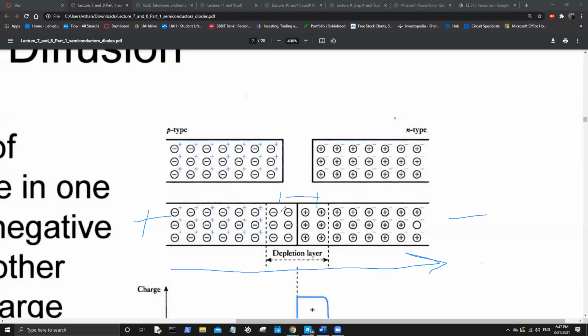But that's caused by an electrostatic effect. Now, I don't know if it's just electrons that do that. You could have an increase of electrons or an increase of positive charges, holes, but essentially it would be the same thing. What happens is your depletion layer decreases. So this equilibrium that used to be equal, you're breaking it. You're adding a hole back here, a hole back here. This isn't intrinsic anymore. You're adding an electron here, an electron here. And the depletion layer becomes shorter because you've essentially returned the charge disparity back to the system on each side.